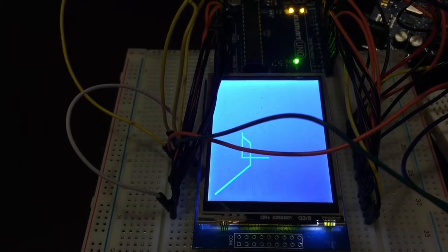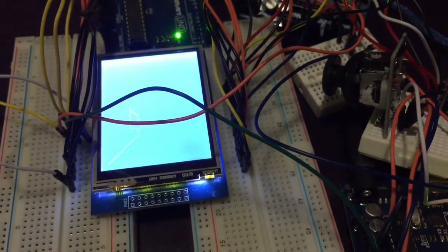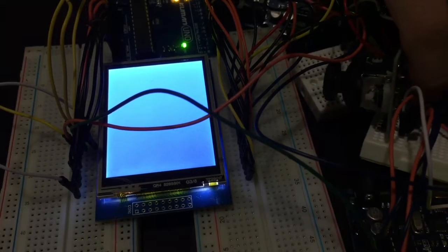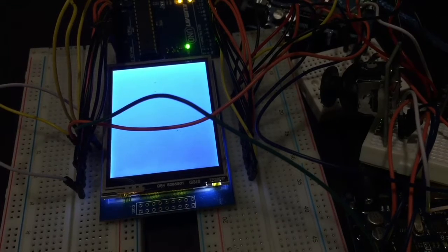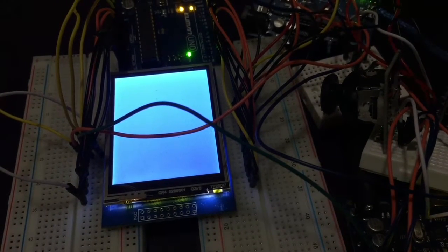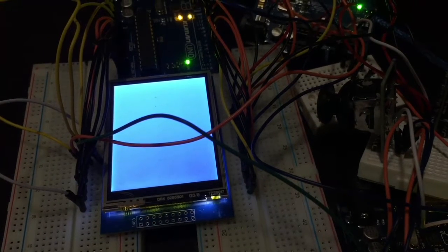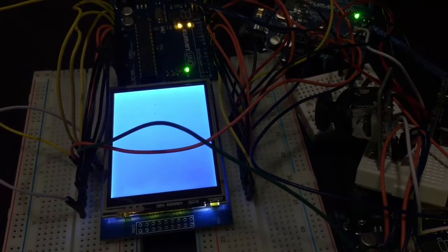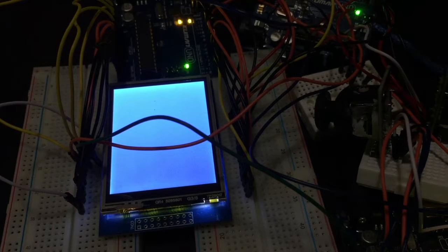It's 8 values for the directions. 1 value is for the analog stick being centered in place, which is kind of just thrown out. And then another value is for a click. The click itself is implemented using an interrupt handler, as we learned in class. When the click happens, an interrupt is called, which flips a global Boolean value. So when the next request comes in, we can just tell master that there was a click recently and then flip the value back.